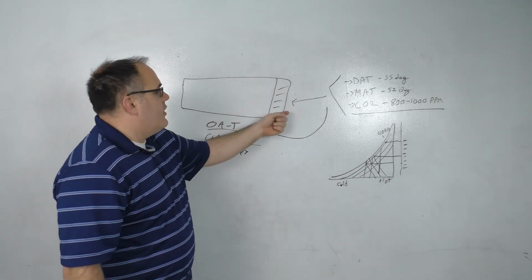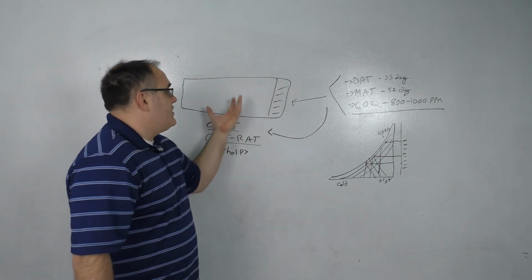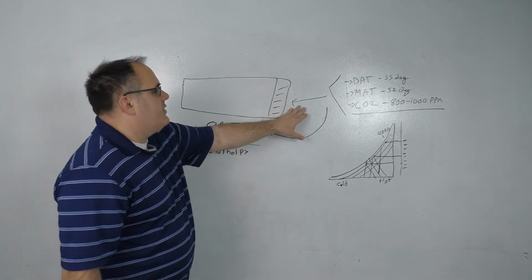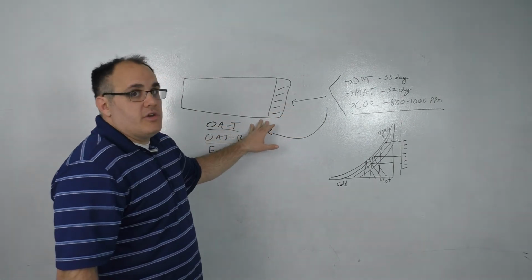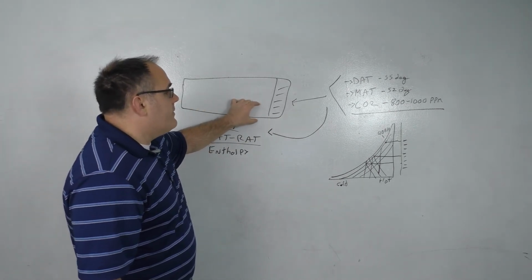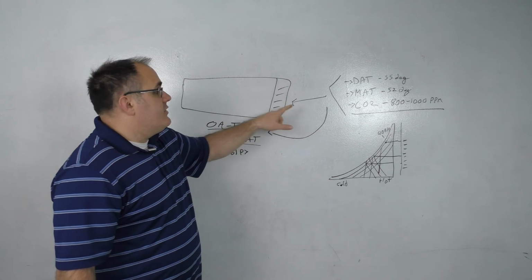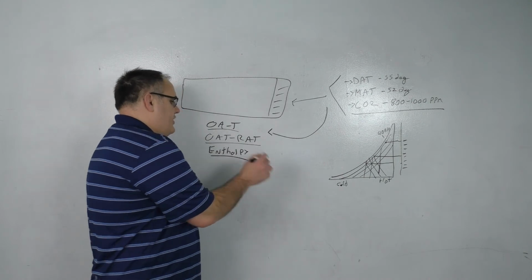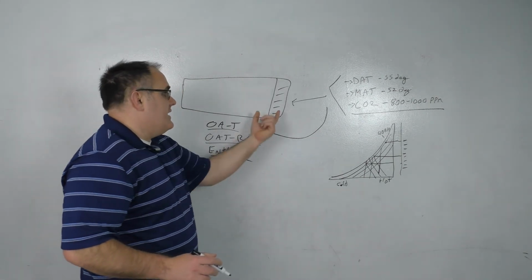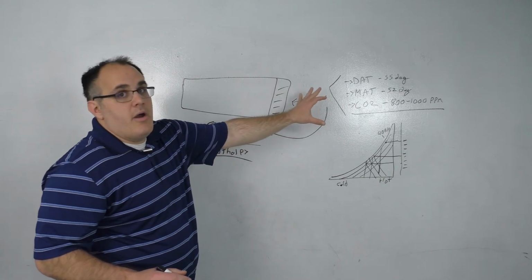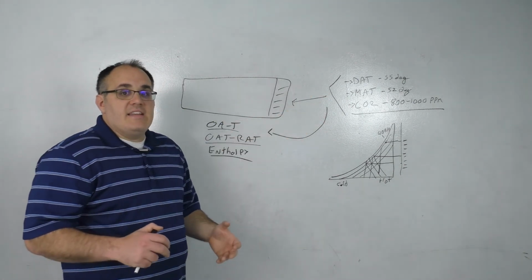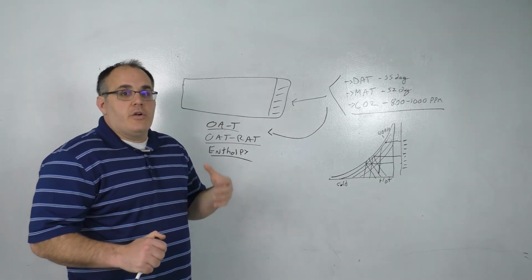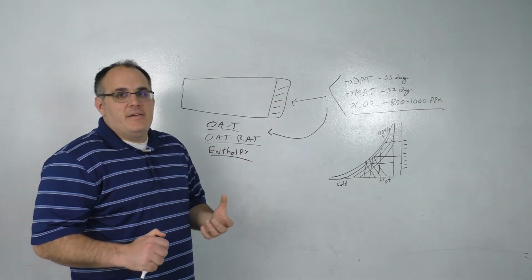And in order for you to realize if you have to use your cooling coil to remove a lot of that moisture and energy, you look at enthalpy. So if the enthalpy of outdoor air is lower than the enthalpy of return air, even though return air dry bulb may be higher than outdoor air dry bulb, there's actually more energy in the outdoor air that needs to be removed. So that is kind of the golden standard way of enabling economizer. And these are kind of the three modes for controlling economizer. And in the last optimization strategy, we'll talk about optimal discharge or differential pressure sensor placement.